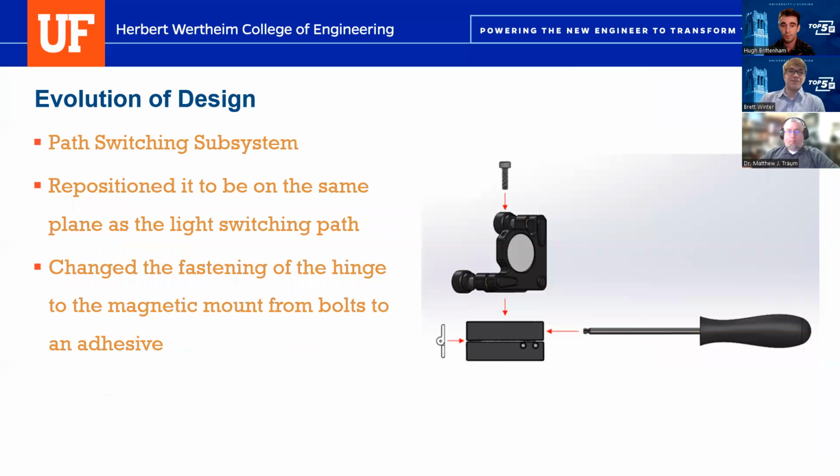The simple task of separating the top and bottom plates of the kinetic mount was also taken through a few different concepts, from actuators to the rotating bases of recliners. The agreed upon design uses a hinge to connect the two plates and ensure that they're both aligned. Initially, the hinge was secured to the mount via screw fasteners, but the path of the plates makes for a relatively low shear stress on the face of the hinge, so we decided that adhesive would be sufficient. As for the material, it was determined that 3D printing the hinge would provide enough structural stability and it would remain low cost.